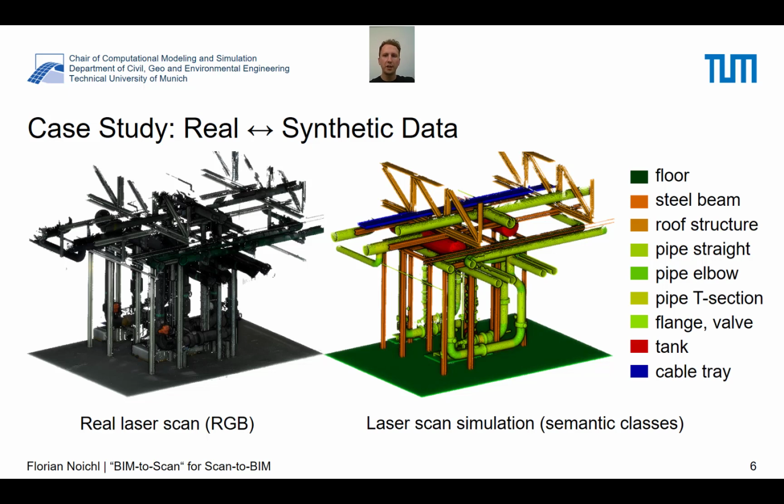After completing the toolchain, we wanted to make a comparison between the real and the synthetic data. To do so, we did a case study in an industrial facility and subsequently performed a laser scan simulation using the 3D model of that same facility. We used the same scanning locations and also adapted the same scanning parameters that the manufacturer provides for the equipment that we used for the laser scan.